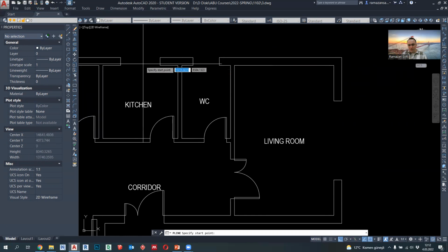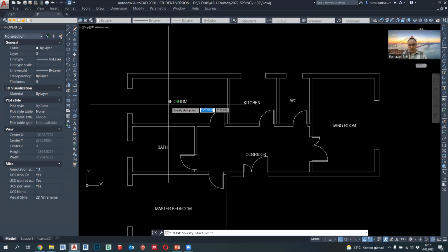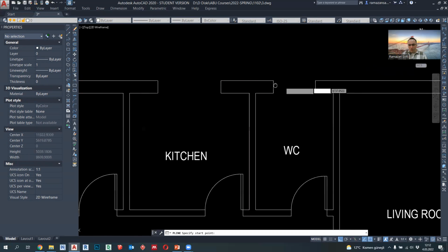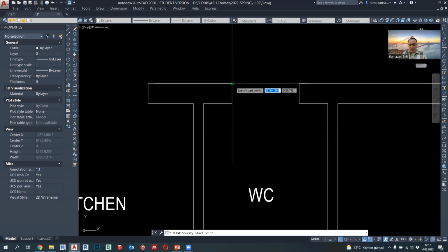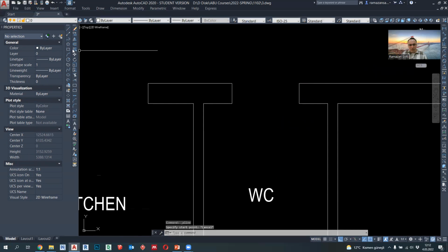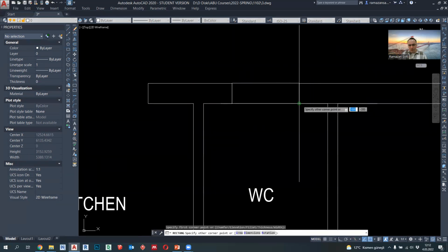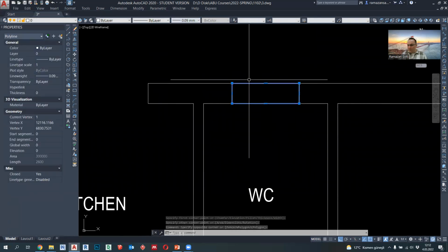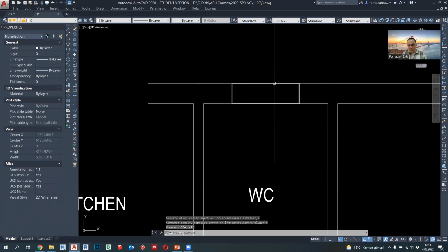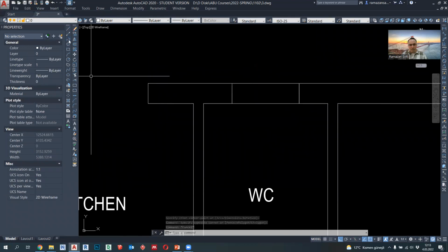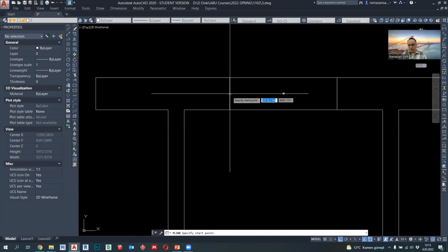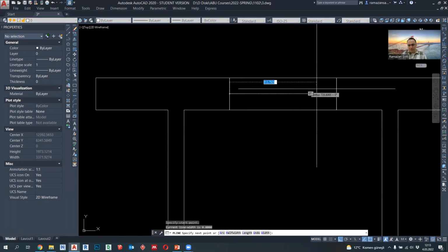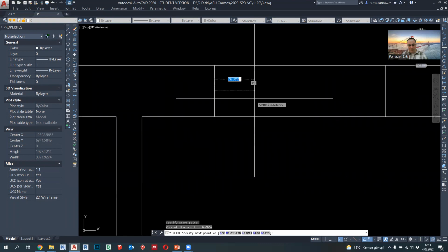Therefore, let's start with the normal windows, regular windows, in other words, having proper sill height and etc. So I will create this rectangle having thin line. Why? Because this will be the sill of the window that I will use, and I will create the frame inside.